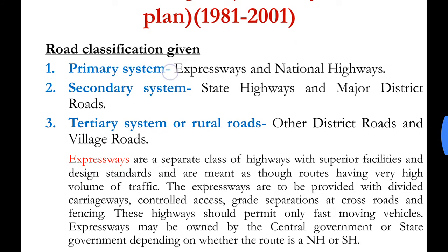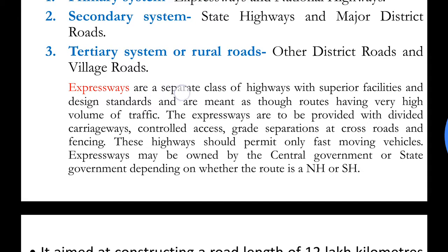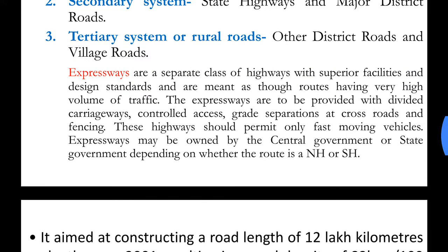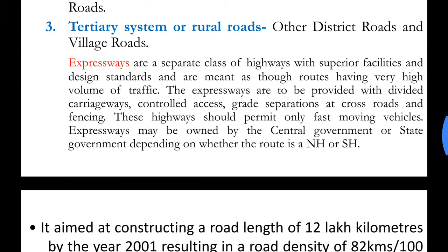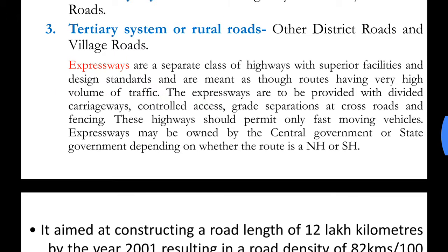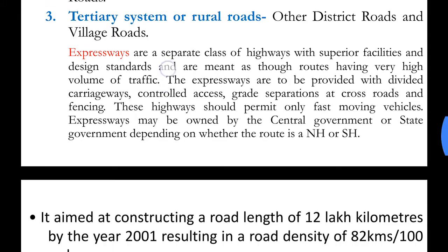Let us try to understand what is meant by expressways. Expressways are a separate class of highways with superior facilities and design standards and are meant as through traffic routes having very high volume of traffic. Basically, they may be either national highways or state highways, but for some specified routes where there is high traffic flow, we convert these national highways or state highways into expressways by providing some extra facilities.